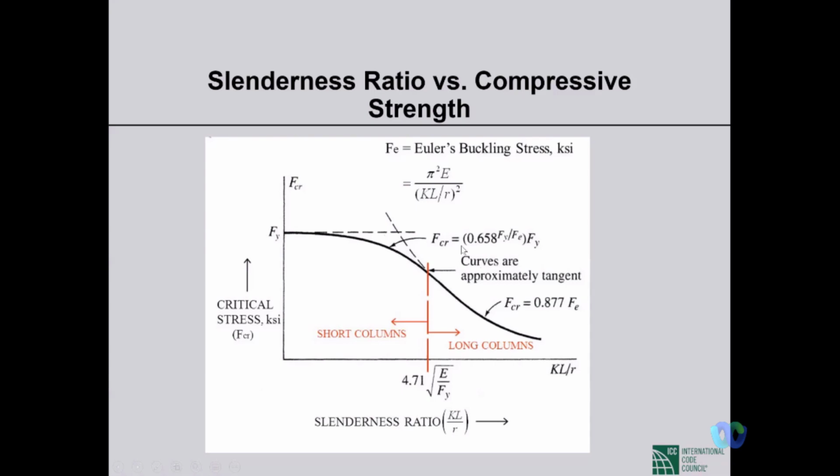This is just nothing but a curve fitting exercise kind of. So for this curve, the formula is complicated. This actually refers to the inelastic buckling, that some part of the section will go beyond the elastic limit, and in the inelastic stage there will be buckling. So this inelastic buckling stage may happen for short columns. So that's why we have two distinct formulas.